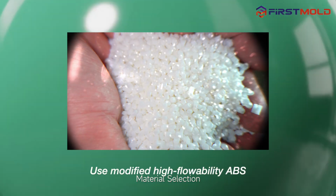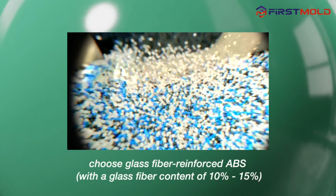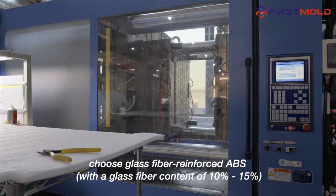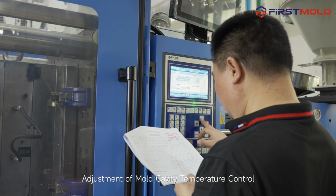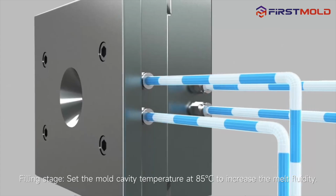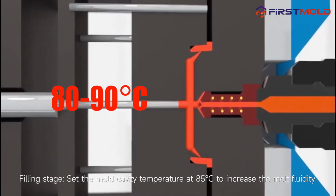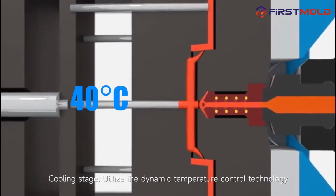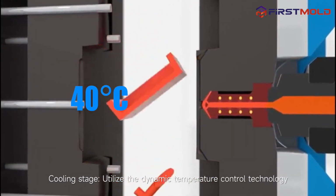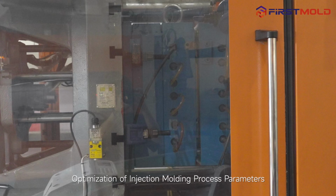1. Material selection. Use modified high flowability ABS. In order to enhance dimensional stability, choose glass fiber reinforced ABS. 2. Adjustment of mold cavity temperature control. Filling stage. Set the mold cavity temperature at 85 degrees Celsius to increase the melt fluidity. Cooling stage. Utilize the dynamic temperature control technology to quickly reduce the mold cavity temperature to 40 degrees Celsius and shorten the cooling time.